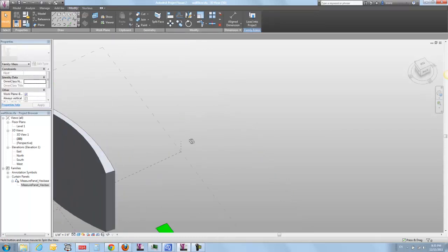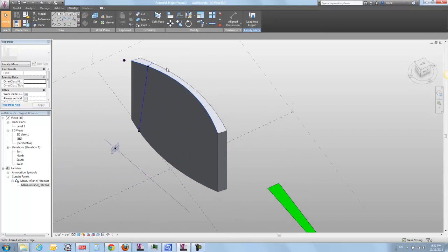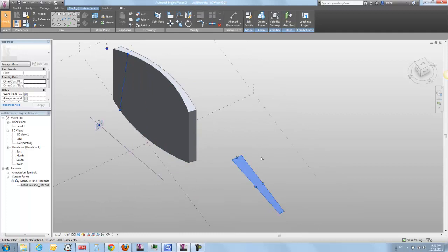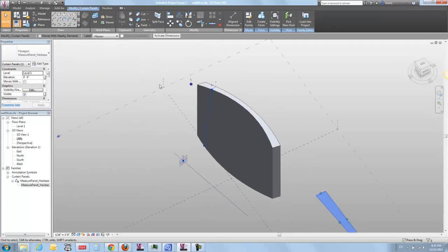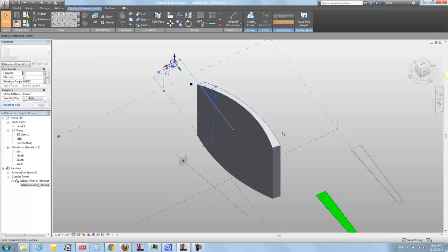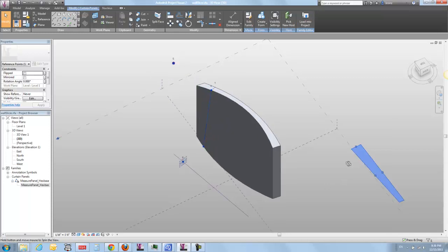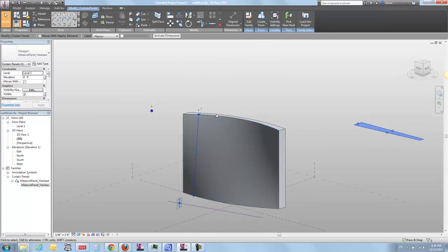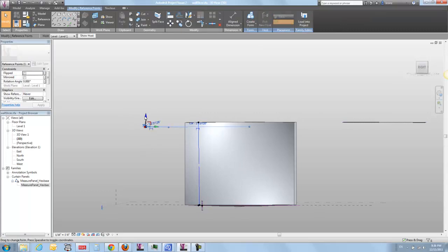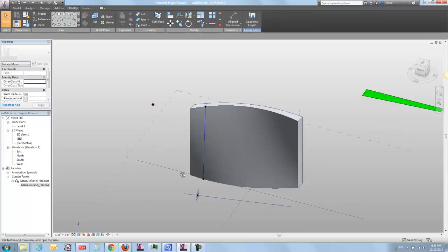So now what I've got is a plane slicing through my regular geometry and creating its representation over here. Now, as I move this point closer and farther away, it allows me to control the placement of where this guy is. This flat representation of this slice is actually hosted on a work plane of this point. So if I take this guy and move it up and down, this guy's going to move with him. So it just gives me a handy way to control my layout here.